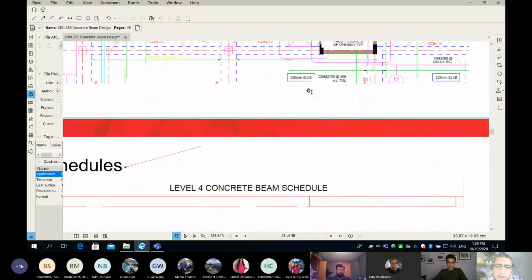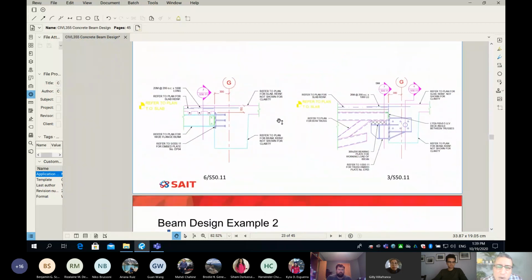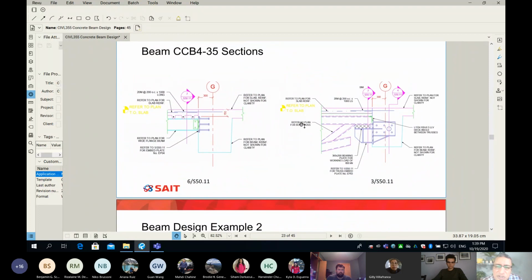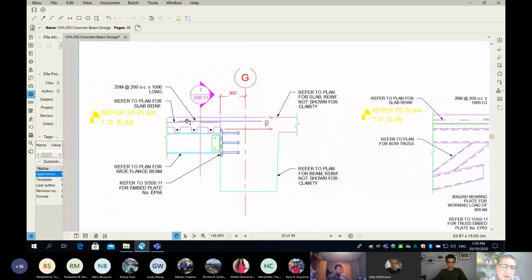Now, again, probably you've seen it already. I'm not sure if you guys are crazy like me. When you go around, you look all the time up and see how things are connected. I myself do that all the time. You guys remember section 3, it shows you how the metal deck is connected to the beam. So here is the beam, which is beam 34 on the 4th level. And if you remember, in the Aldrich Center, it is simply concrete topping on top of a metal deck. And there are some steel joists connected to your beam.